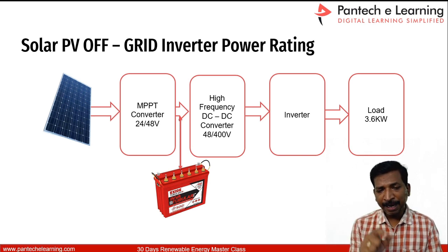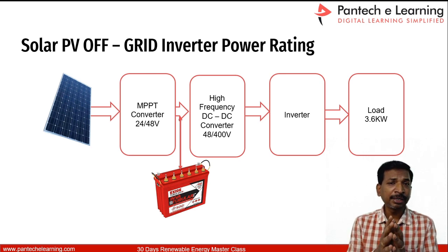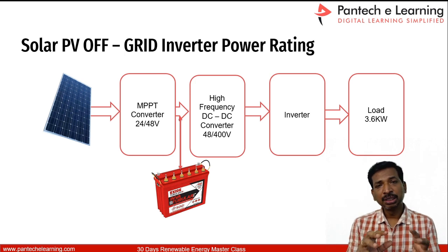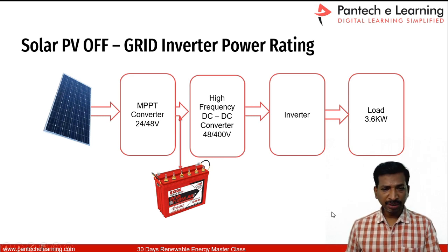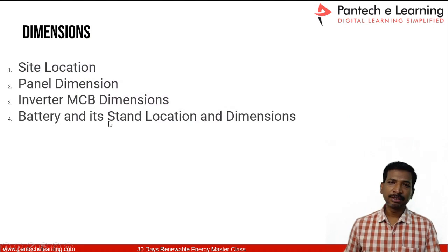And here the battery is a toxic battery that will release toxic gases. So we have to provide complete, proper ventilation to avoid those issues. In that situation we have to identify the locations of the components, right? So this information we have to get from the customer.